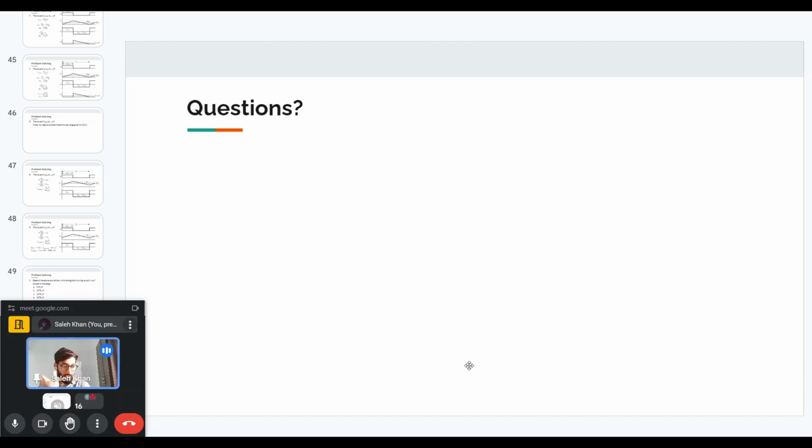Yeah, PFC is not a requirement. It depends on if you want to have unity power factor, because otherwise you will draw non-unity power factor as well. You will draw some additional current, which can lead to more losses. So PFC is not a requirement, but I was just suggesting what is commonly used.